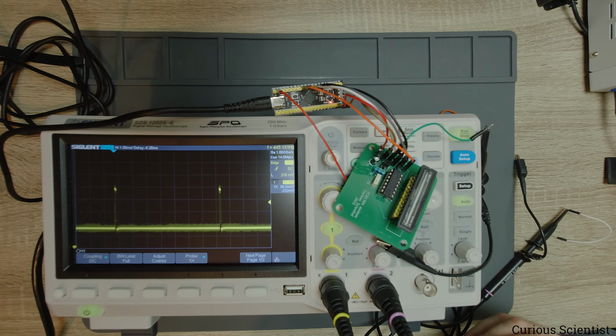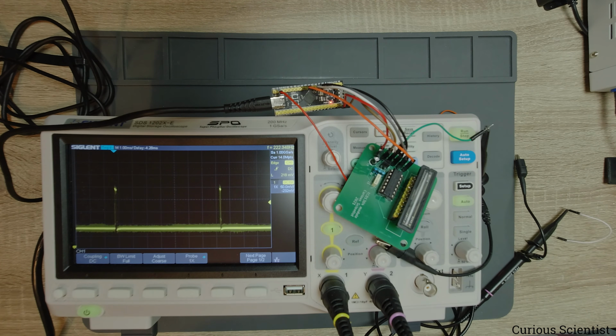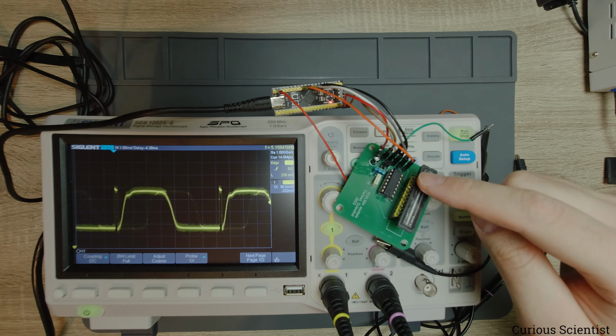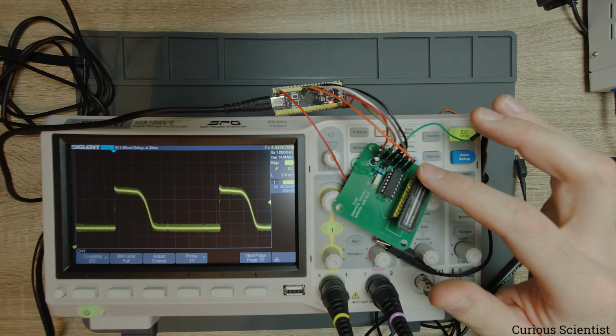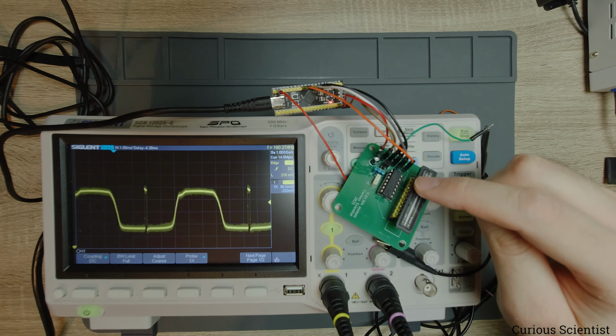There is need for the knowledge of how to program this thing. So you can set up the integration time properly, and you don't need to cover the CCD, because if you use short enough integration time, of course you will not have the problem of the overexposure of the linear CCD.